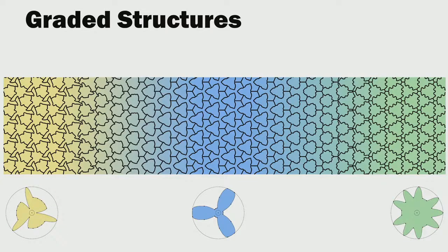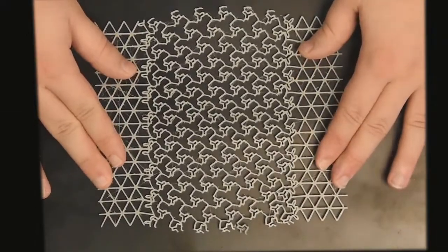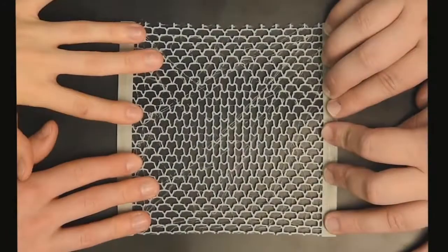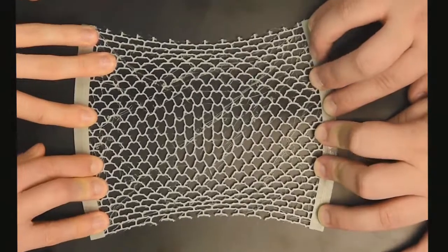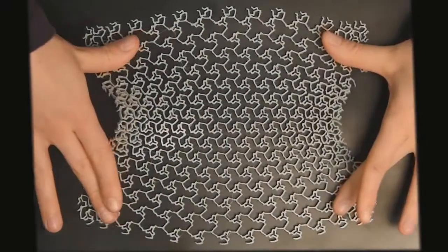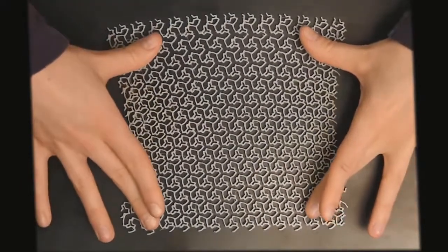And then, another application for this interpolation is that we can now create spatially varying continuous tilings. So here's a very short clip that illustrates some of these tilings that we made. Here's an auxetic structure, negative Poisson ratio. Here is a heterogeneous structure that in the middle has a lower stiffness in this horizontal direction. And then here's another one that wants to bend out of plane because of the strongly auxetic behavior.